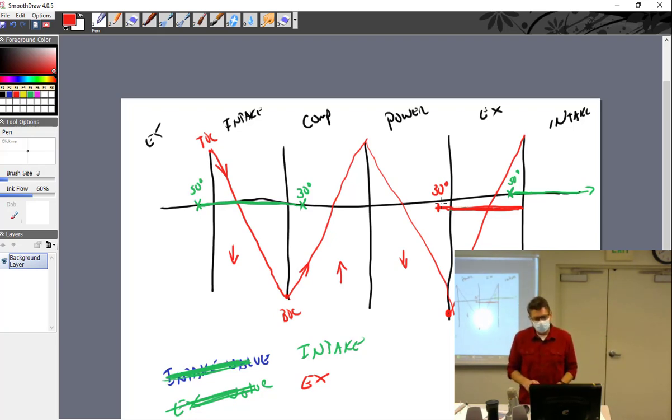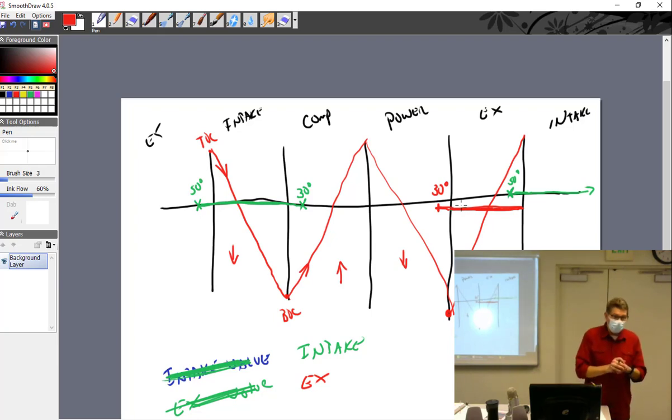All right. Well, of course, you already know the subject matter, but what is the biggest fear of every aircraft owner? Stuck valves. Stuck valves or burned valves. Either which way, it's our exhaust valves. Everything we think about, oh, my poor exhaust valve. The whole rest of the airplane could fall apart as you're flying, but we worry about our exhaust valves. So we got to get these exhaust valves to cool. And the way an exhaust valve cools is by being closed. So the longer it's closed, the cooler it's going to be. So you have to kind of weigh this in there.